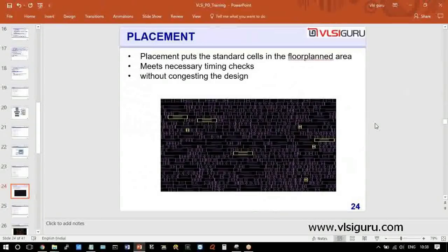So what is a rail? You go to railways, you see the track, there's always a constant difference throughout India, broad gauge or whatever it is. Similarly, you have the same height, which means it carries the VDD current and the ground current. Now when a standard cell goes and sits there, the standard cell's VDD and the rail will actually overlap, and your power is going to flow through the source, through the gate, through the drain to the next cell. That is why we have standard cells.